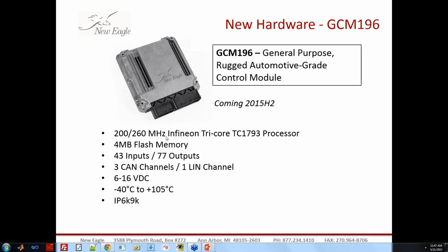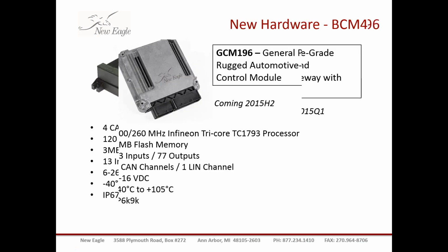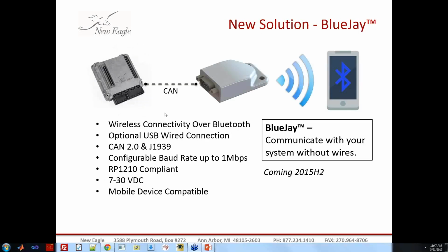That is how you get from DB9 to the CAN bus. The BlueJ will also have that. It's got the DB9. I'll show you the picture of it here. You would use one of the DB9 to 10-pin SmartCraft hub adapters to hook that into your system.